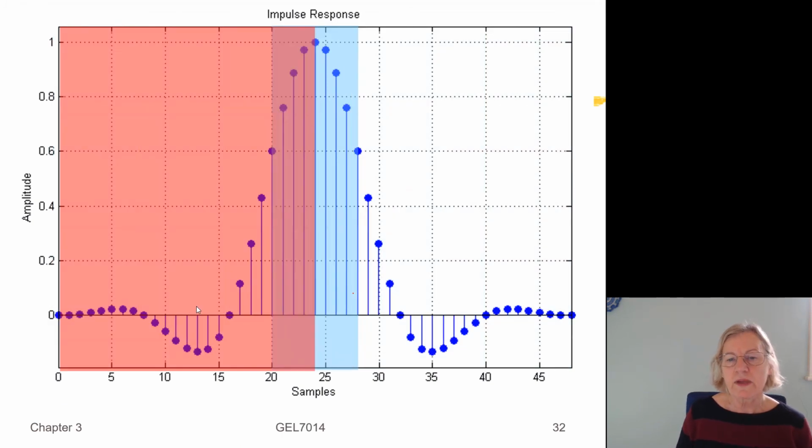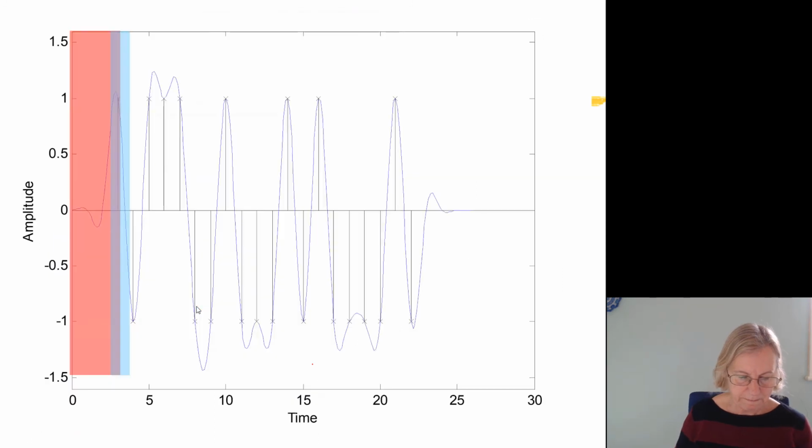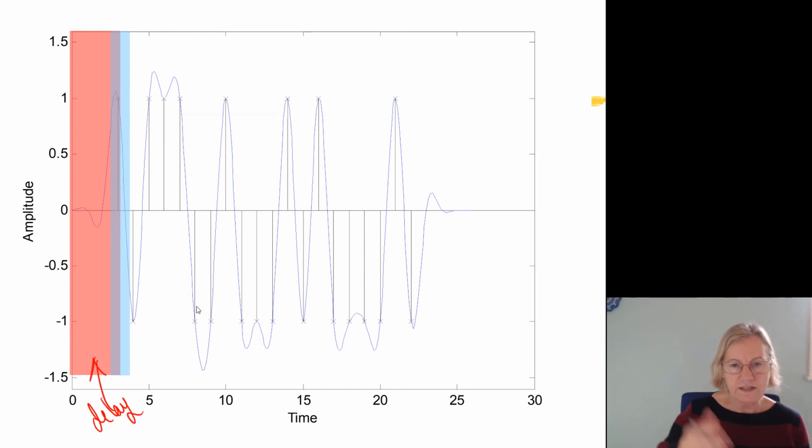And the delay, again, we have to introduce a delay of 3 so that we have the peak of our pulse actually occurring when we want it. So this is a trace of the sequence that is generated inside of Matlab, and we can see that there's this startup time when things don't quite make sense, when I've introduced my delay for things to sort of catch up. And then we can see where the timing is of the symbols.